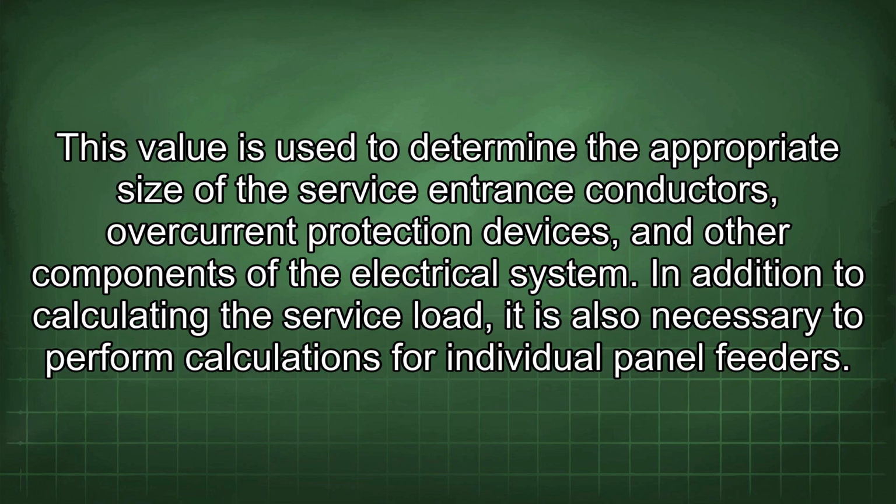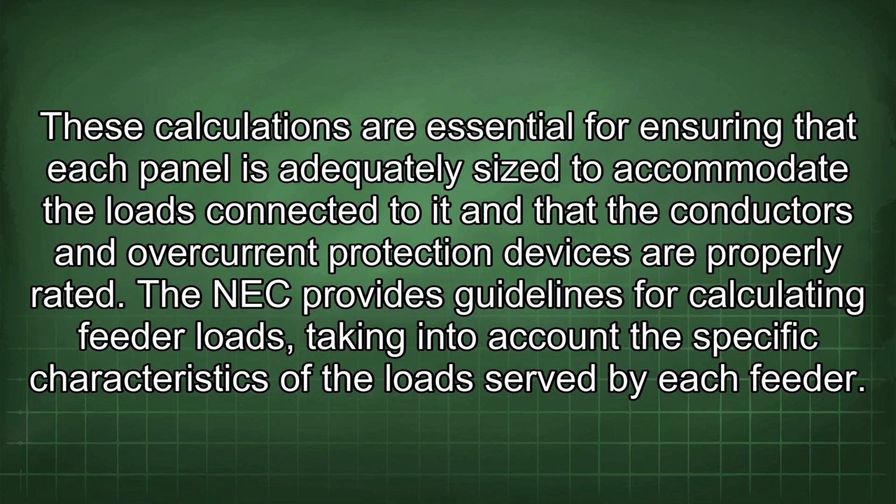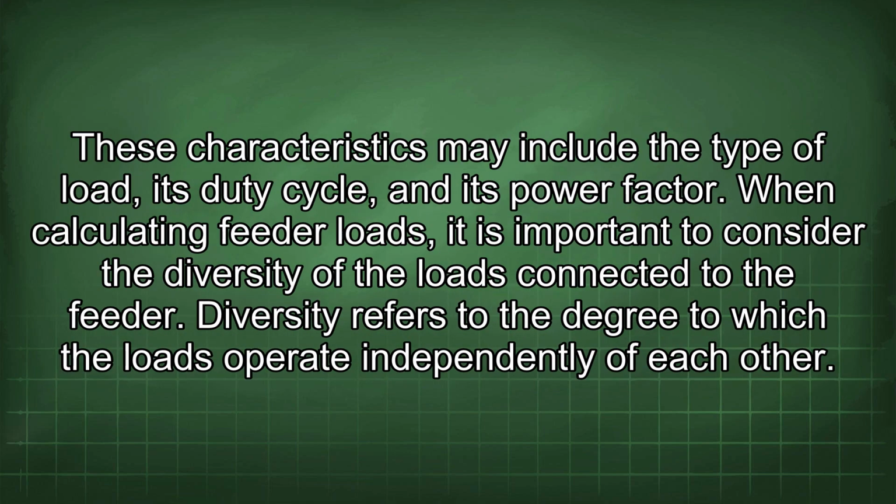In addition to calculating the service load, it is also necessary to perform calculations for individual panel feeders. These calculations are essential for ensuring that each panel is adequately sized to accommodate the loads connected to it and that the conductors and overcurrent protection devices are properly rated. The NEC provides guidelines for calculating feeder loads, taking into account the specific characteristics of the load served by each feeder. These characteristics may include the type of load, its duty cycle, and its power factor.